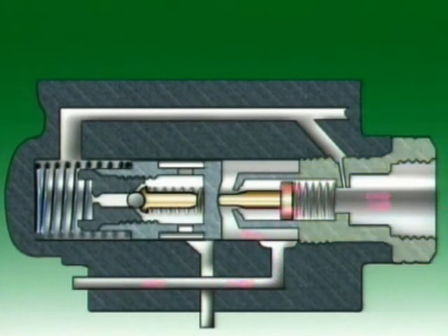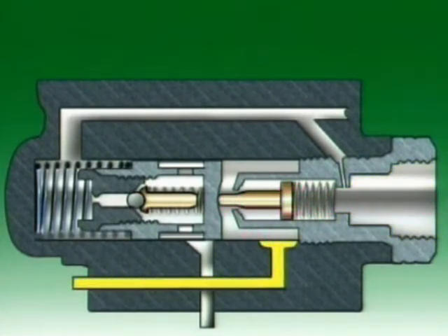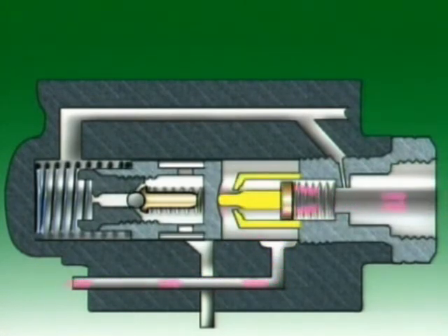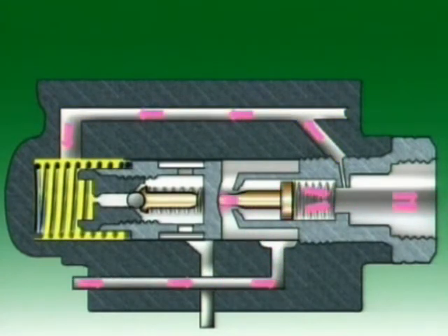Discharge ports direct the fluid to the outlet and then to the steering gear. The outlet fluid pressure is slightly lower than the internal high pressure coming from the pump. This drop in pressure occurs as the fluid flow passes the needle and orifice in the outlet fitting. This lower pressure is transmitted through a bypass fluid passage to the spring end of the control valve.